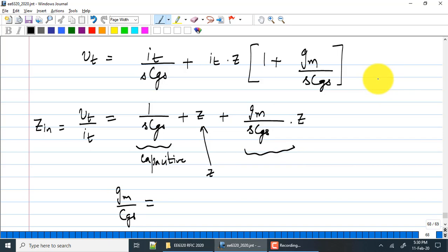So now this is the transition frequency of the transistor, 2 pi times ft in gigahertz, where ft is the transition frequency. So it's a good thing he brought up CGD, because this is an approximate definition of transition frequency.